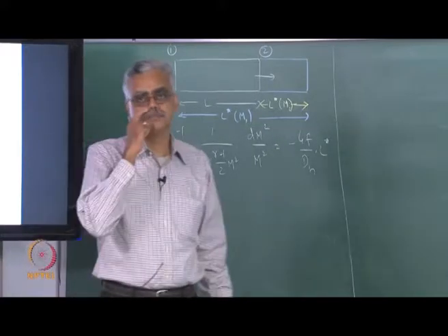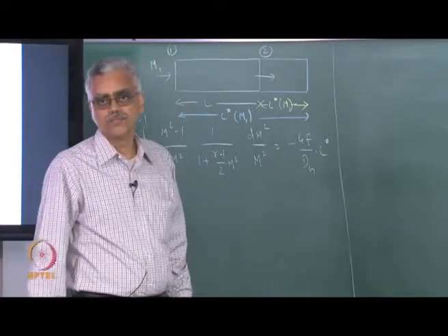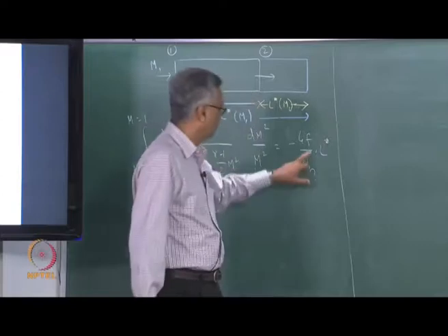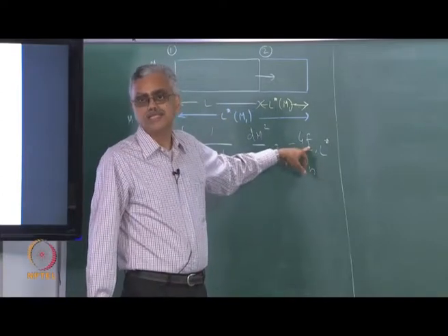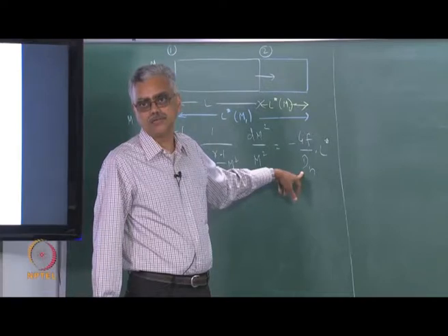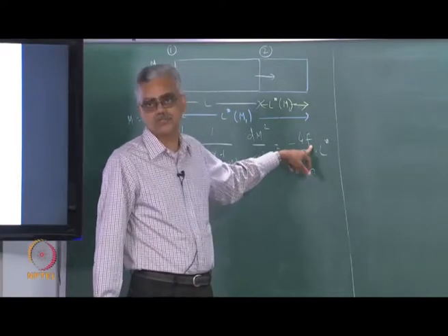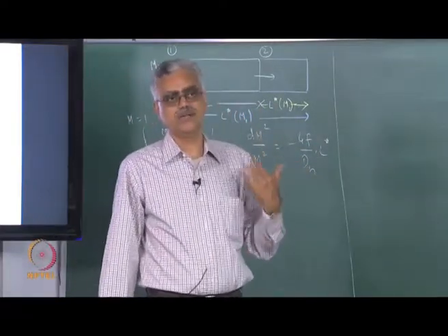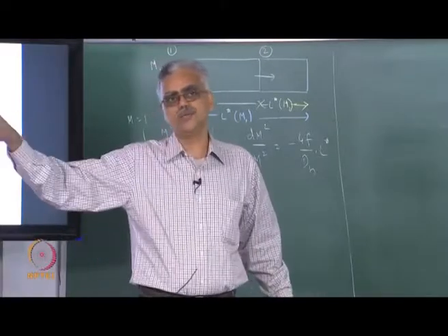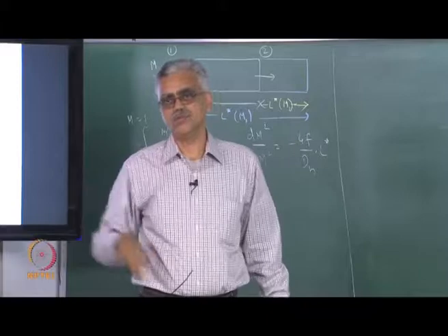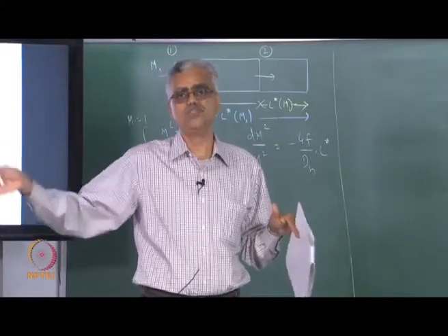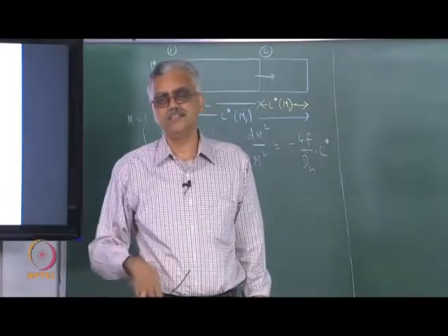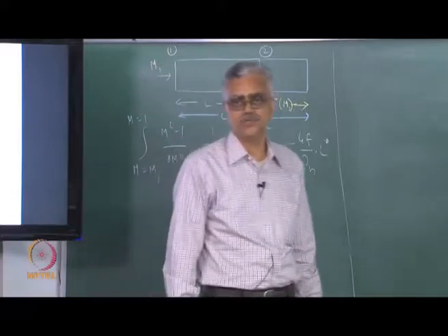All these frictions will depend only on hydraulic diameter, or will it depend on the aspect ratio? The friction coefficients depend only upon the Reynolds number. The friction stress depends upon the hydraulic diameter, but the friction factor depends only on the Reynolds number. And you will notice that for the kind of speeds with which we are working, the Reynolds number based on hydraulic diameter will be so high that you are essentially operating in a region where the friction factors are constant. So, in fact, you are far to the right on the Moody's chart, where you notice that the friction factor is independent of Reynolds number. That is the kind of region that we are operating in. So, that is a very good engineering approximation to use.